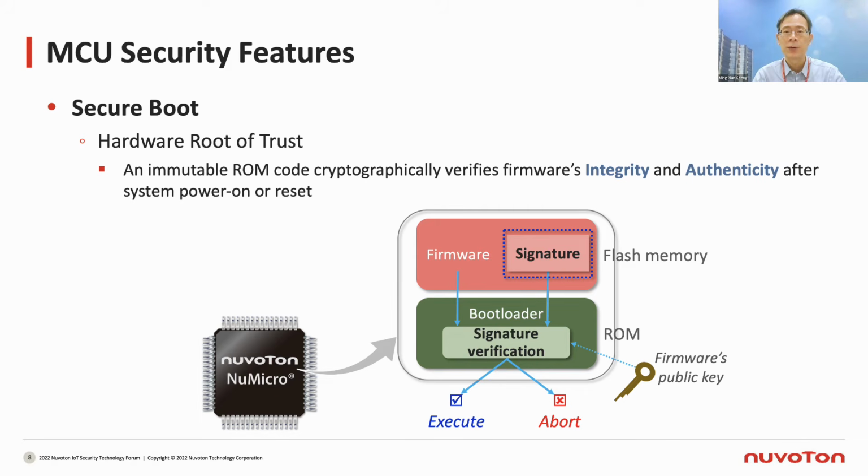If the verification result is not correct, the secure bootloader will prevent the firmware from executing. Through the verification of digital signature, secure boot can guarantee the integrity and the authenticity of a firmware, so it can be said to be the hardware root of trust.